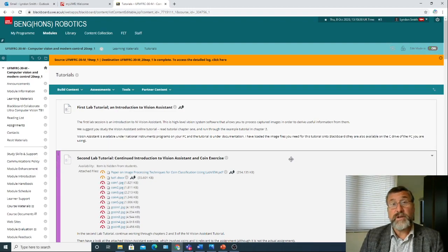So rather than having lines of code, which you have in traditional languages such as C and BASIC, in a G language you have icons, which you place on the screen, which are like subroutines, and then you have wires, which you connect between these subroutines, which data flows along. And that's the way you control the operation procedure of the program, by means of the data flow along wires. So it takes a little bit to get into that idea for some people, but once you're into it, I think you'll realize it's easier and more intuitive to program in this language than it is in most other languages.